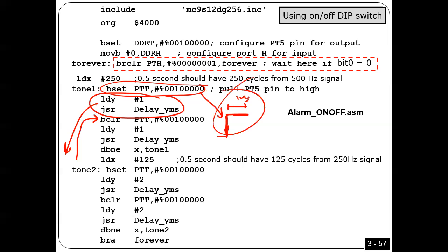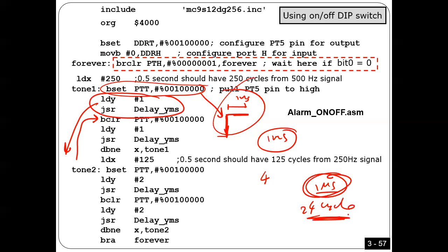I'm not sure if you can even see it on the scope, but you can try. Because for 1 microsecond you need 24 cycles. Assume in the worst case the ignored instructions create 20 cycles. They are much less.